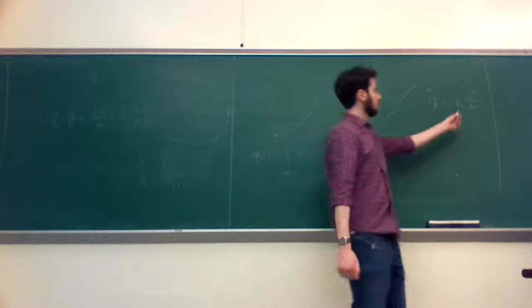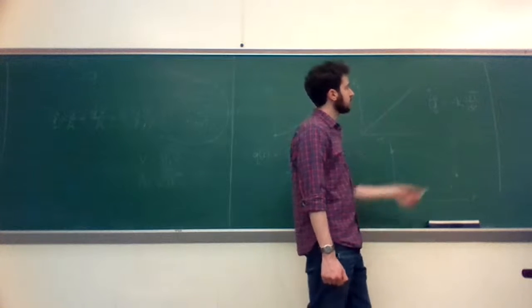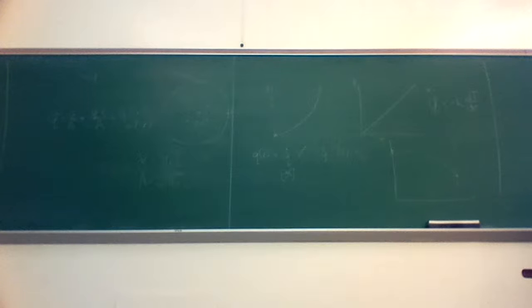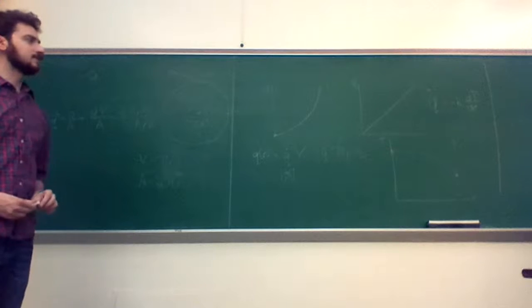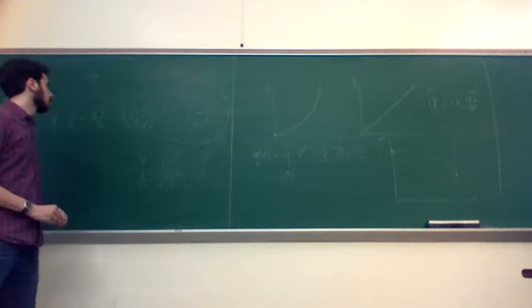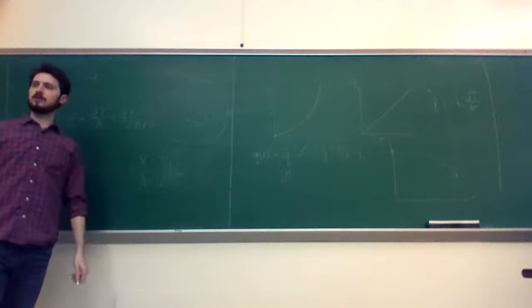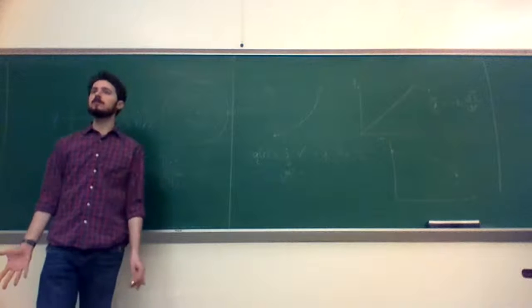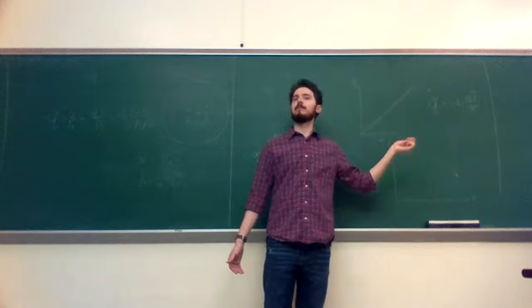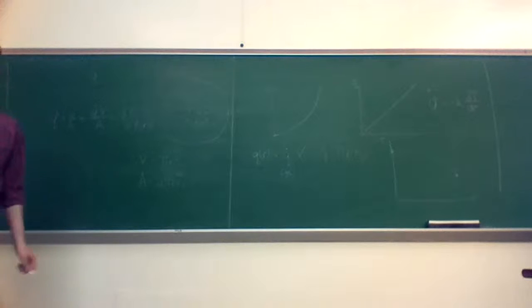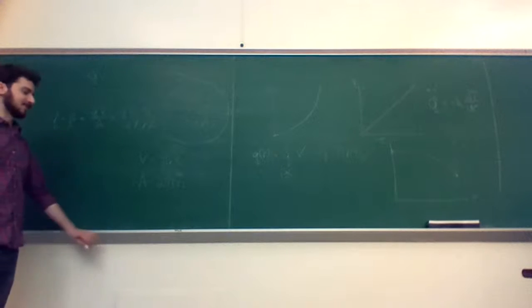It's just kind of inspection of the governing equation. So I think that's that problem. I hope it is. I'll check with Professor Burke, but I think that's basically everything you would have needed to do for problem 4. And that's the critical thing, is you didn't need to do some energy balance nutty thing. You know what's happening with V, you know what's happening with A, you know what's happening with Fourier's law, and you just sketch it out. And then there's a little bit of intuition too, right? We know it's not going to go to zero temperature on the outside, unless you labeled it as zero. If you're at absolute zero on the surface of the cylinder, then you might.